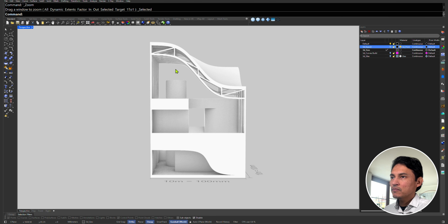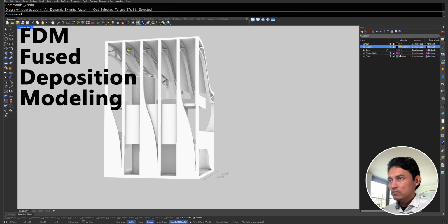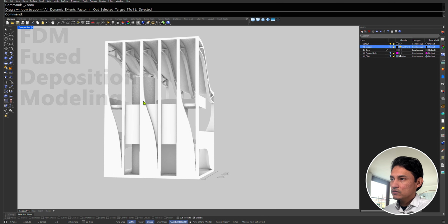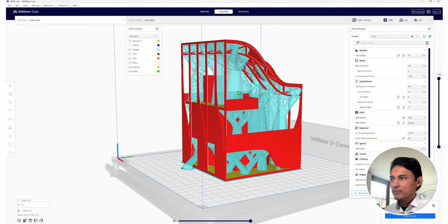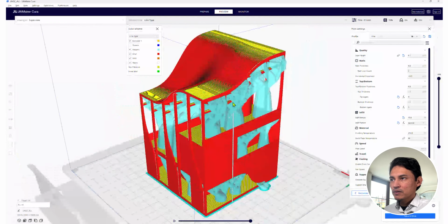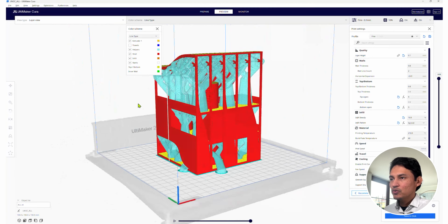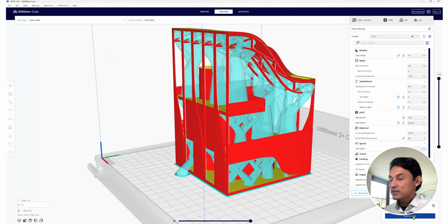Avoid overhangs. Let's say you want to print a model that shows construction features like slabs, trusses, columns and so on, like in this example. When printing with a FDM printer, short for Fused Deposition Modeling, you have to take into account that extra support geometry will be required to build these overhangs, thus increasing the printing time. And besides that, this extra geometry has to be carefully removed, usually leaving traces at the bottom side of the overhang surfaces, which is not optimal.